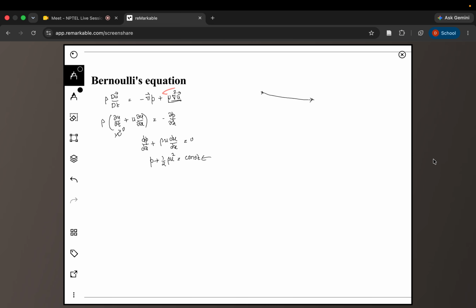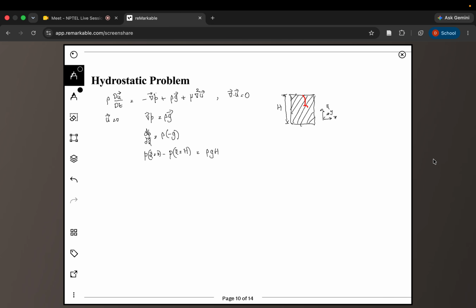In the previous case, I know that fluid flow is not happening, that the fluid is stationary. So if I were to measure velocity at any point, it will be zero. Using that fact, I was able to reduce the Navier-Stokes equation to this equation and determine the pressure. A similar strategy, similar technique will be used next week when we first derive the energy equation and then move on to boundary layer equations, where people have done experiments and measured certain quantities, basically the terms inside this equation, and from there we will eliminate certain terms, which gives us simplified equations, which we will solve to determine different quantities of interest.